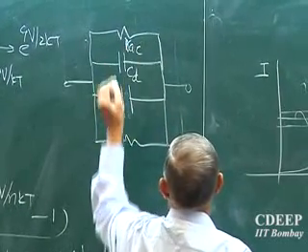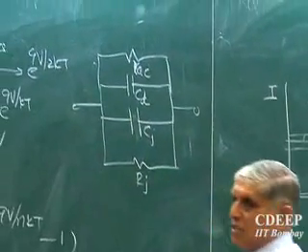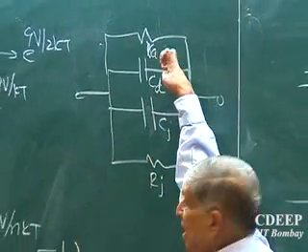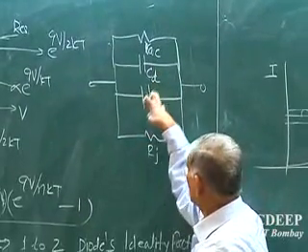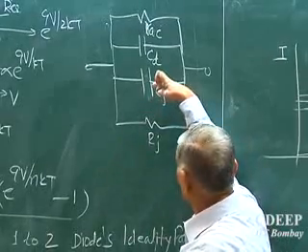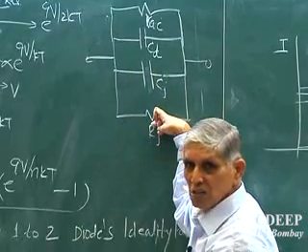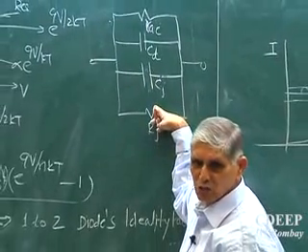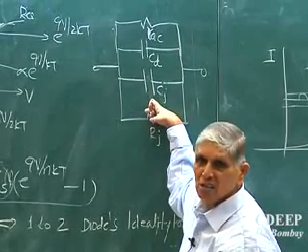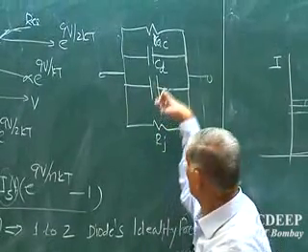R_AC you call it, and R_J, C_J. This is the equivalent circuit of a diode: R_AC shunted by R. Now, do you get the point? Something I am putting here: under forward bias, this term will vanish. This R_J, C_J will vanish. In reverse bias, there is only the capacitive and resistive effect, R_J, C_J. R_J is R_R. How much will that be? Tens of megaohms. C_J will be of the order of a few picofarads.